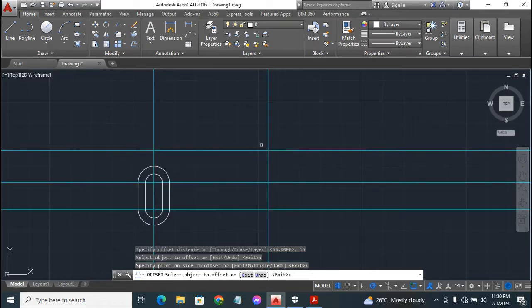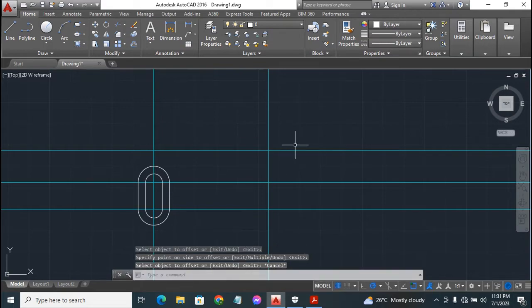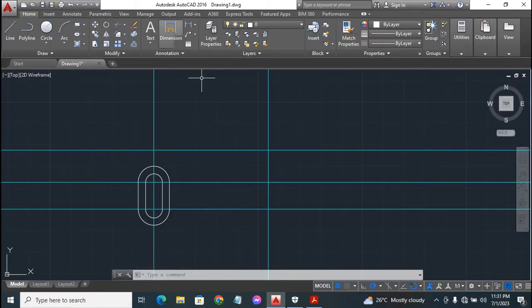So this point of intersection of the construction lines is going to serve as the center of the circle you just saw in our PDF document. Yes, the measurement of that circle is 7.5 millimeter radius. So I'll go to the draw ribbon, click on circle, then I'll lock my cursor to the point of intersection of these construction lines. As you can see, it's not locking there.